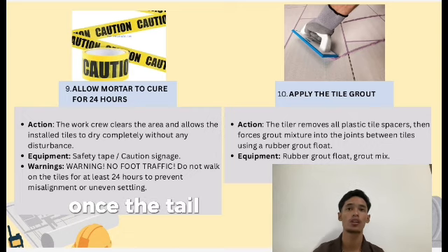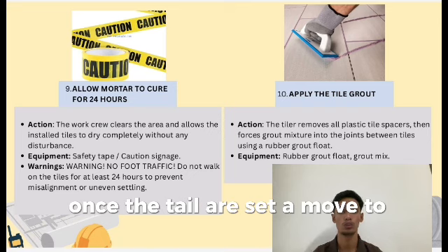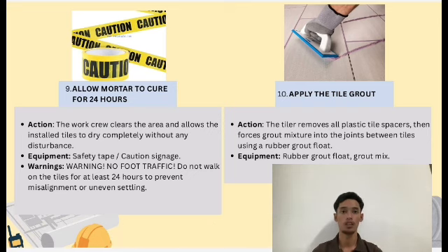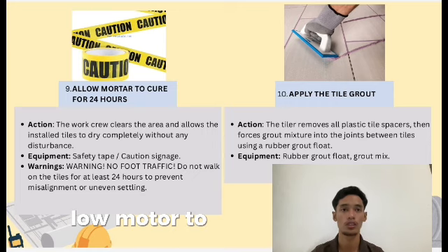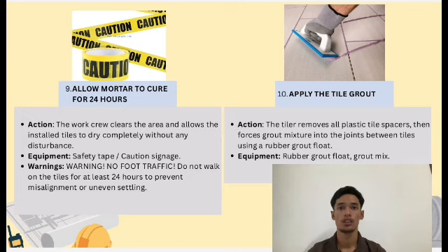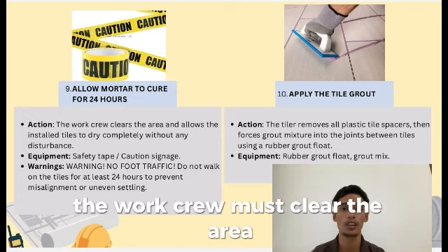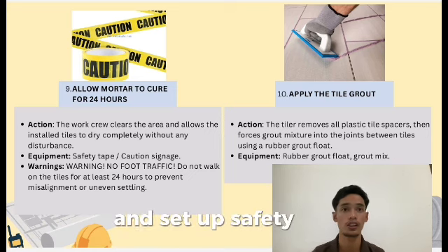Once the tiles are set, move to step 9. Allow mortar to cure for 24 hours. The work crew must clear the area and set up safety tape.